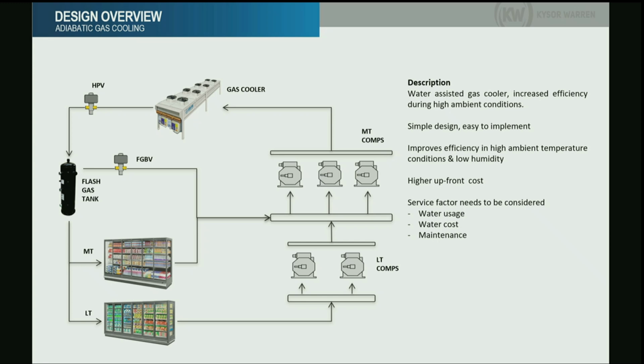I'm not going to tell which one is better. I will just provide the concepts and somebody decides what they want, right? So this is adiabatic gas cooling. The easy way to do it, I missed that part, is you have an air-cooled gas cooler. You basically remove the connections going in and out from the gas cooler, and then you put the adiabatic gas cooler, and you are done. It's really easy to make the change in this case. That is another reason why it's very commonly used.